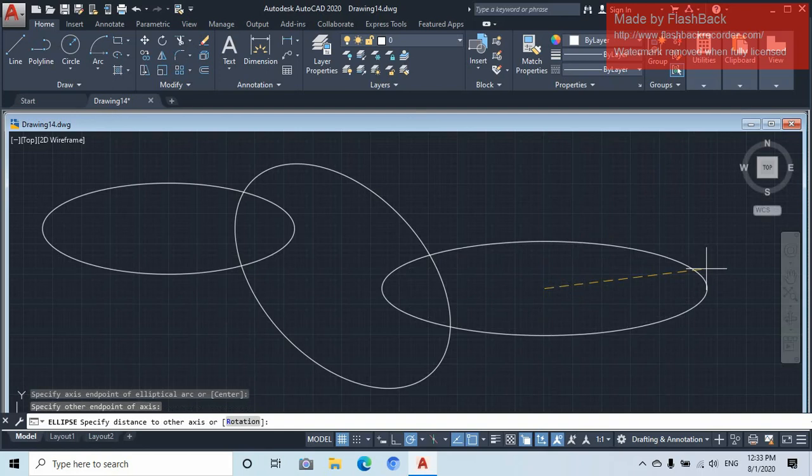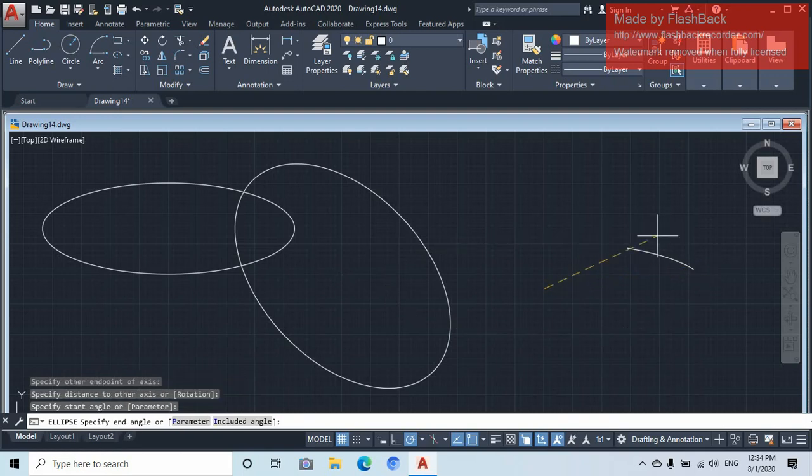Then now you will click at the second point, then your cursor will still be active. It will need you now to click at the third point. This third point is to open up, because this one is an open ellipse arc. Let's see how we can open the arc. Then you click now on the third point, depending on where you want to open your arc.